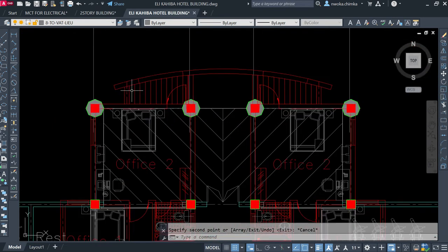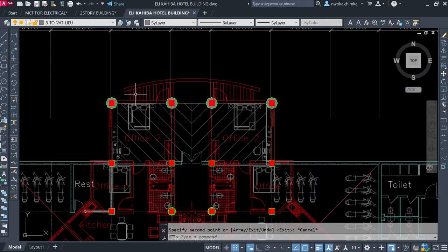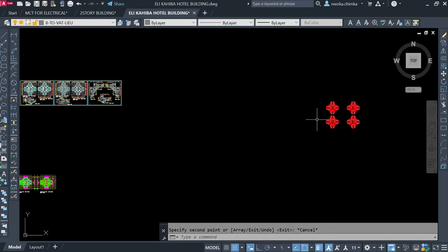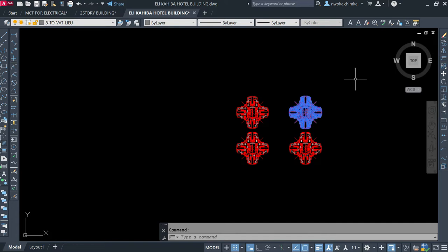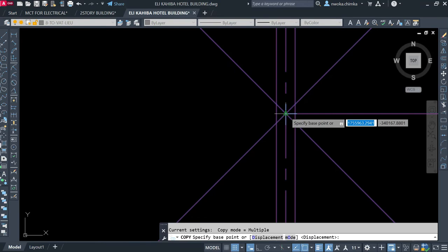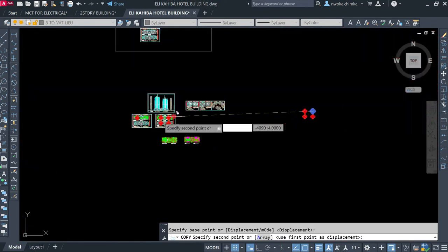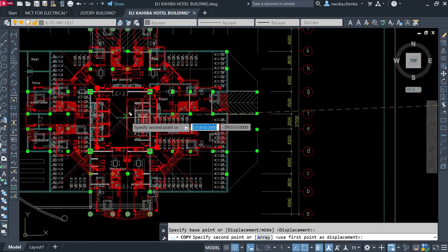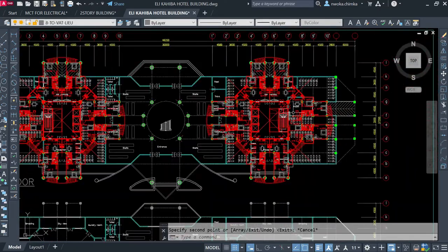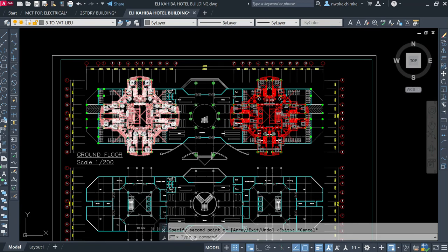As you can see, the cantilever, you can also see it right here. So we also did the same thing here and copied this other one also. Copied this one too using CP, located and found the exact reference point, and took it to the other side also, and placed it here. Okay, so this now gave us the two reference points, as you can see here.